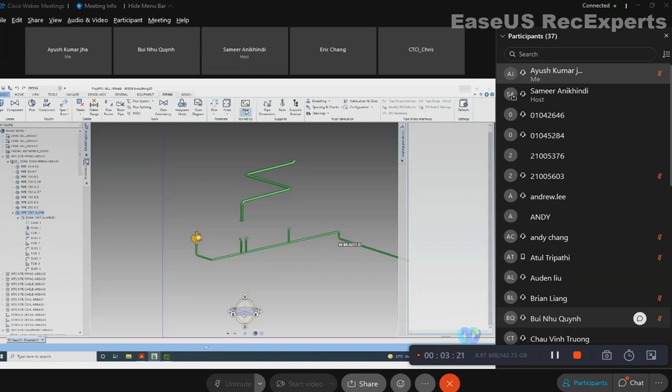Okay, so in order to change the spec bore, in the modify menu, there is modify for pipe and all pipe hierarchy or modify by branch hierarchy. There's very slight difference here. In this option, branch option, it will not change the spec of the pipe, but only for the branch. In here, it will change for pipe and all its members. Click on this pipe.